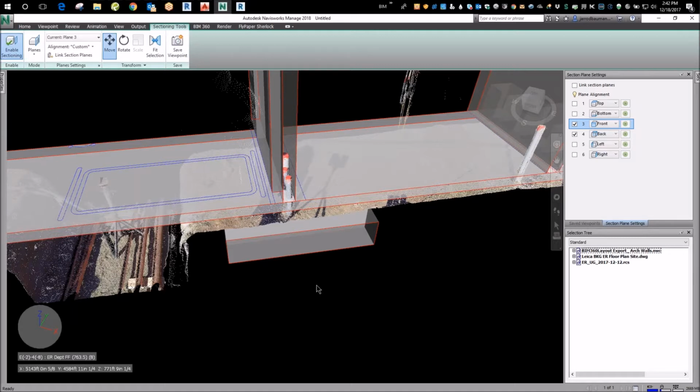So Mo is pretty sophisticated. Their BIM, they produce points out for their total station, and that guy, he's the only one who didn't have screw-ups out there or major, because he was using the control that was still good to sync up his total station. Everybody else, Couts and the electrician that measured off the grid lines that were bad, they ended up in the wrong place.